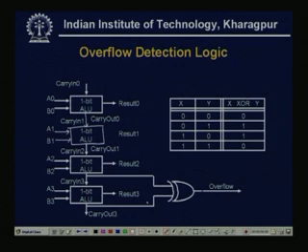Now, if we take the XOR of carry in 3 and carry out 3, it will detect the overflow. So, this is the overflow detection logic.